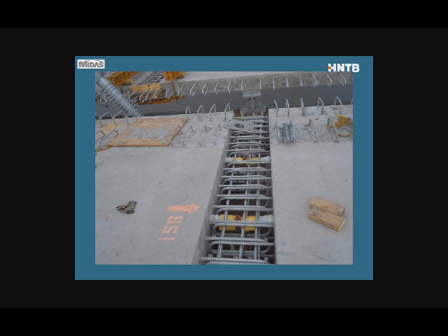And this is a view of the deck of the Lake Champlain Bridge, and this used a similar scheme as the Happy Hollow Park and Zoo Bridge. What you see here is the deck panels. There's a transverse joint. You can see the post-tensioning tendon, so similar to Happy Hollow, the deck is post-tensioned longitudinally. Here, precast deck panels were used. That is advantageous when you support your deck on steel stringers, because you take out some of the creep effects. And so this system has more redundancy, because now we have the deck, the tie girder, and the stringers all participating in the deck load path.